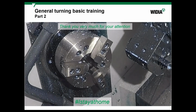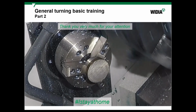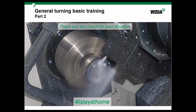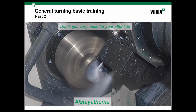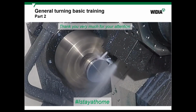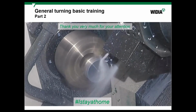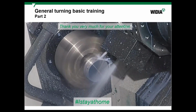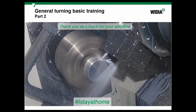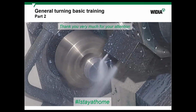The first choice is to change something with the tool itself. The second, the chip breaker. If it's long overhang, if there are vibrations, choose a sharper chip breaker, for example, ML. If there are no big deviations of the profile of the surface of the skin, if there is a skin at all, so if there is no instability in the workpiece, just overhang, you need to choose a sharper geometry and start with WP25.